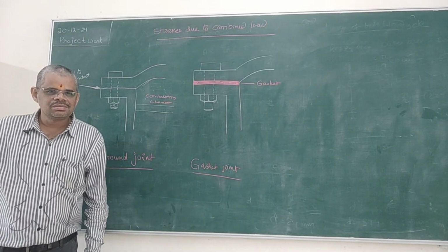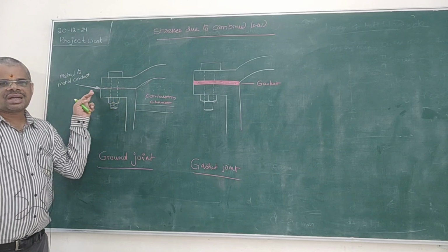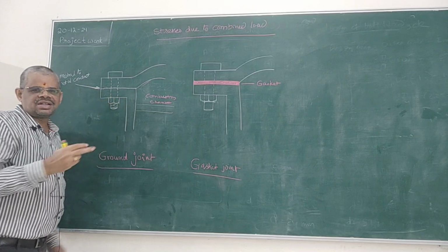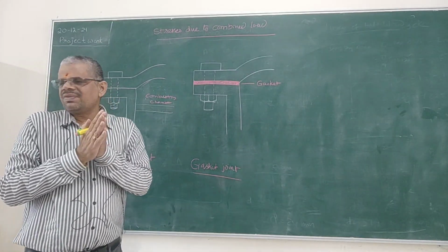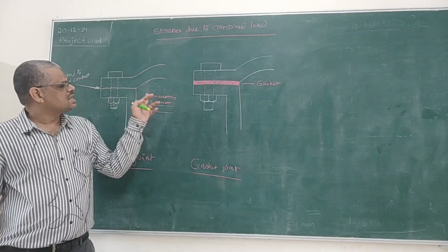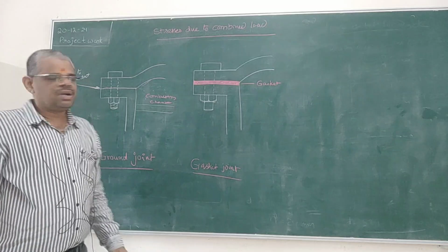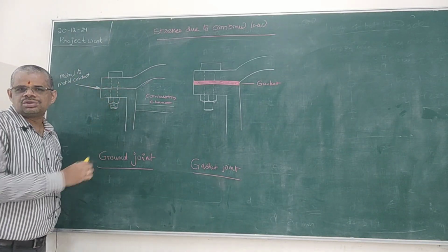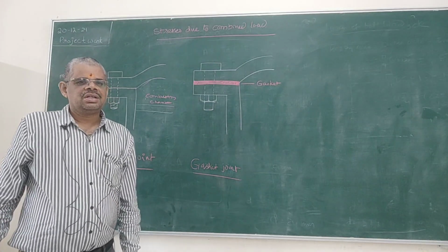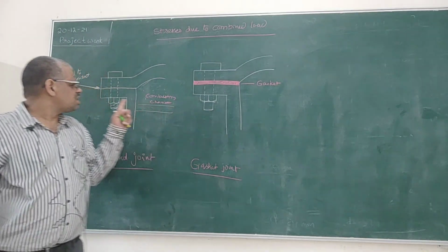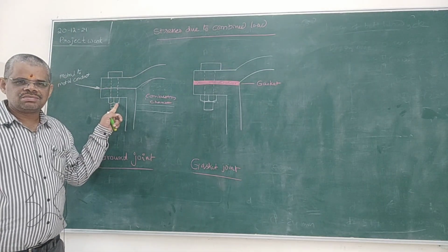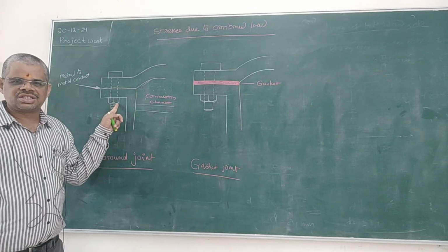Is it right or not? The combustion gases may escape through the gap. So that's why these two surfaces must be perfectly joined together without any gap. Even a small gap will lead to the leakage of the fuel. So that's why we must use maximum load to tighten it. That load is known as the load due to initial tightening, and during the process of tightening this bolt may fail, it may break sometimes. Okay, so that we have discussed in the first case, right?